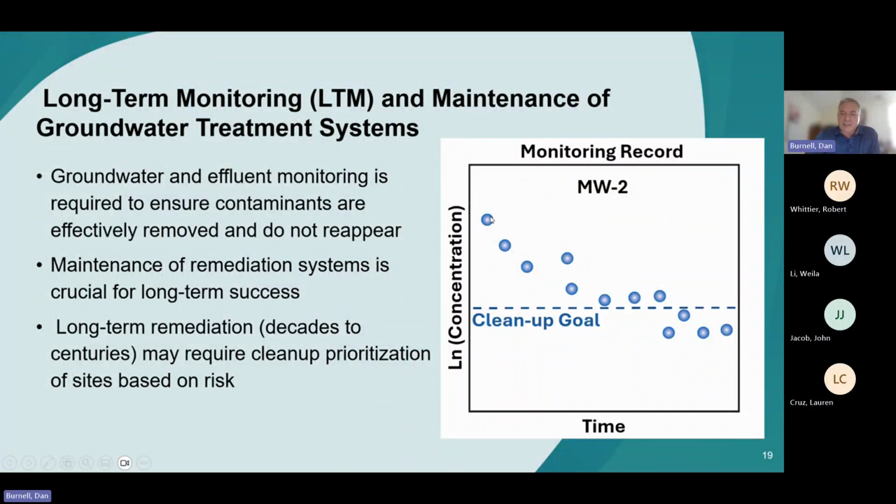And so, for example, the goal is to eventually get the contaminant concentration levels below the cleanup goal. But even then, subsequent monitoring will be performed to make sure that there's no back diffusion and they don't go back above the standards. And so there'll be a period of a year or more of monitoring to make sure that the concentrations remain below the cleanup goals here.